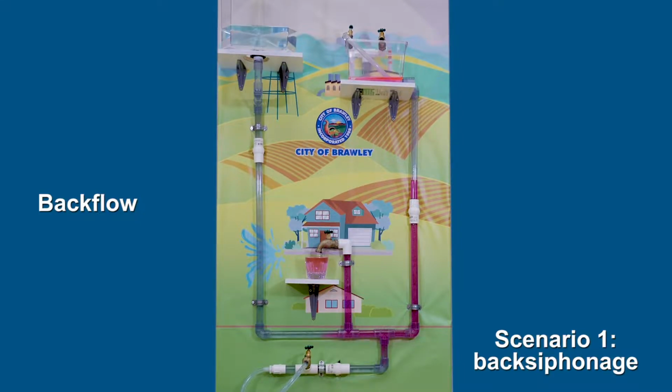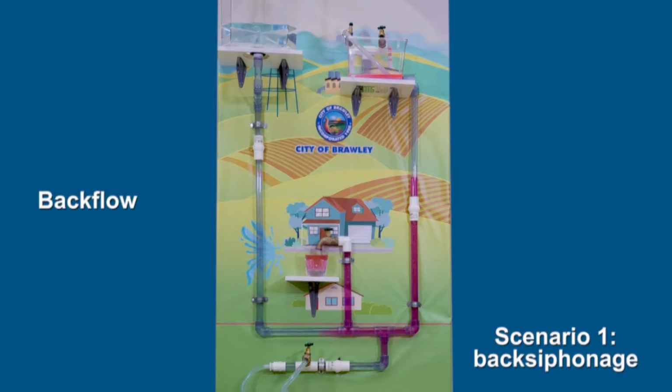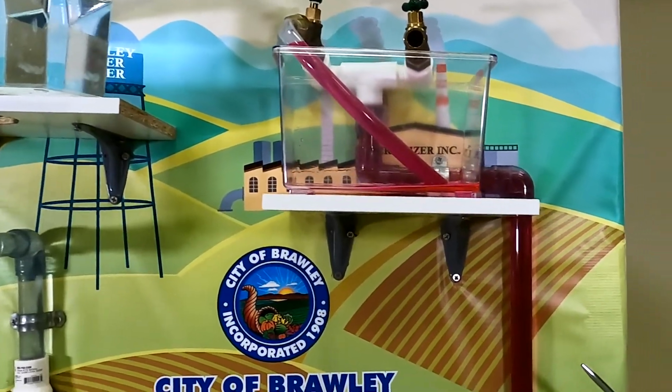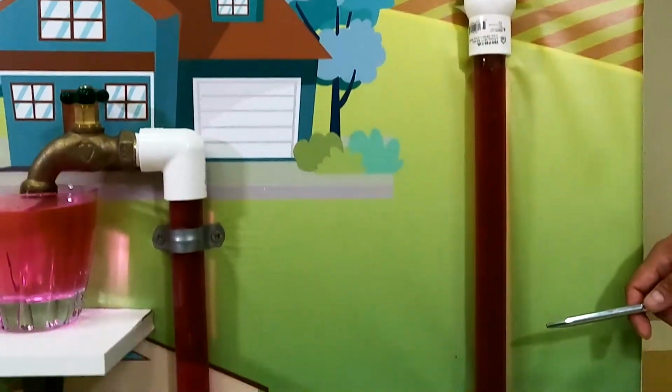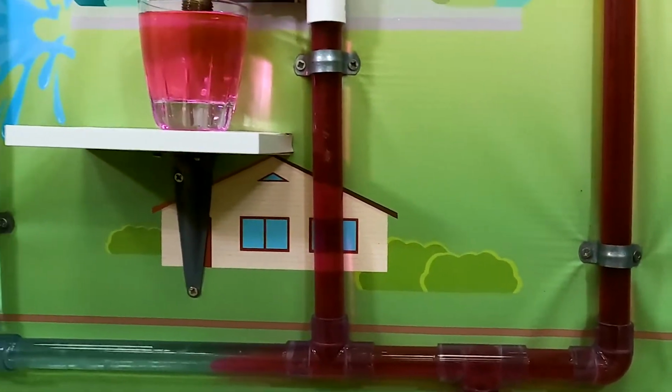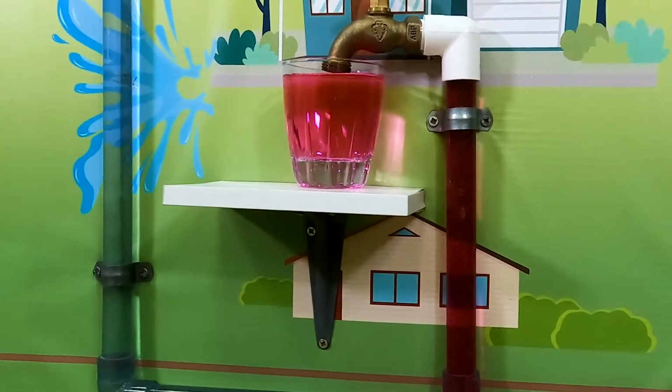With a backflow device, the chemical would have been stopped from back siphoning and contaminating the drinking water supply. The burst main is repaired, and the city has its water supply restored. However, the network still needs to be flushed to ensure all traces of the chemical are removed, and sometimes the main has to be disinfected as well before the water is considered safe to drink again.